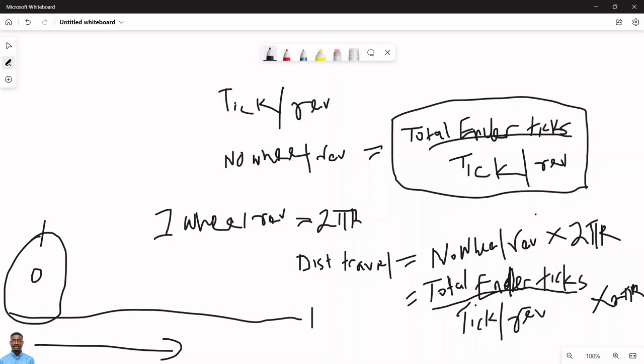However, this method for calculating the distance covered by the robot might not be very effective. It's not even that it might not be, it's not effective, because if the wheel of the robot is slipping, it's not covering any distance, it's just slipping on the same spot, the encoder will keep ticking, thinking that the robot is moving, whereas it is on the same spot. The wheel is just gliding on that same spot. So that is why the science of localization is very, very important. Even if the encoder has ticked a million times, the robot can still be on the same spot.